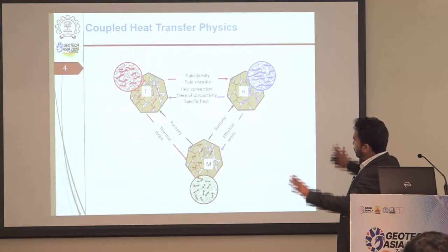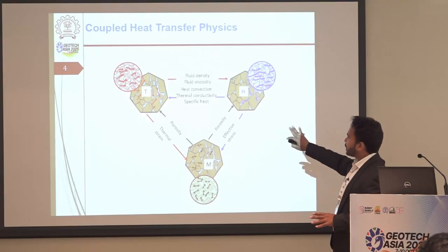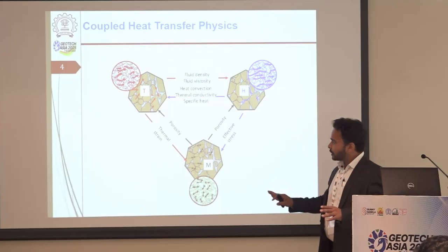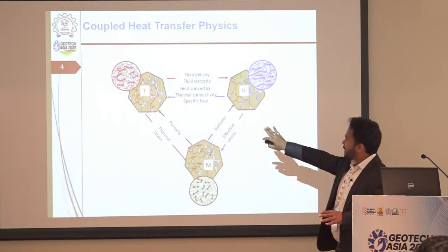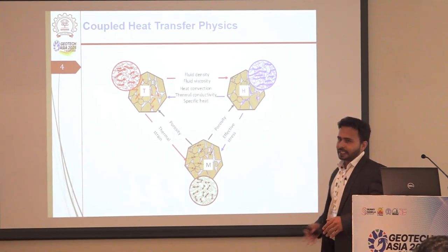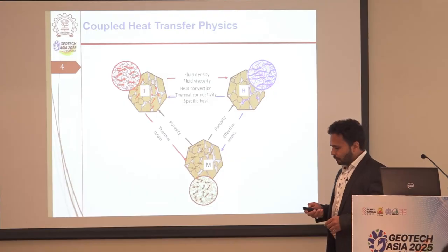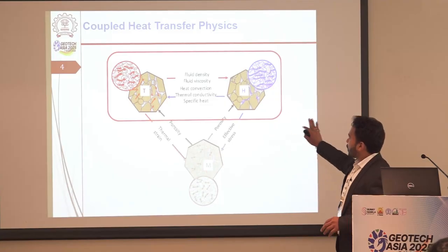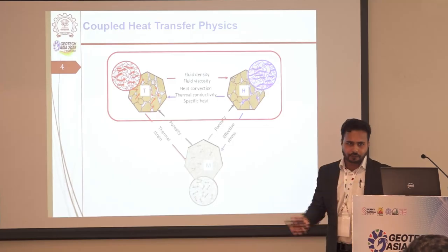So this whole process has 3 major components when it comes to geotechnical engineering: thermal, hydraulic, and mechanical. When we talk about deep foundations where temperature is involved, we have to investigate this THM, famously called thermo-hydromechanical coupling, that influences the pile capacity and then soil-pile interaction on the surface. But for this presentation, I will mostly focus on the thermo-hydro coupling, how the temperature and hydraulic components are going to influence the process.